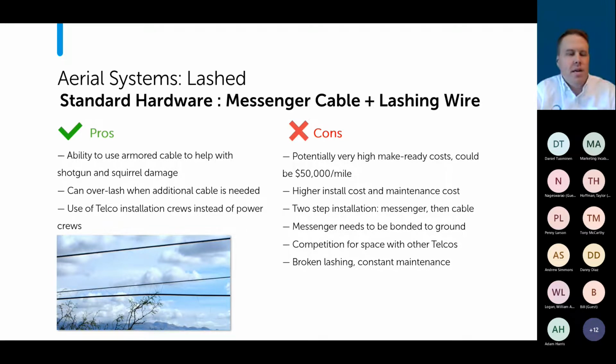You're going to have more truck rolls just to go out and relash and tighten up that cable onto the messenger cable. So again, I don't say all this just to bash strand lash as not a good approach and not a good place to put cable. There are certainly areas where it is a beneficial place to have your cable located in regard to a fiber to the home build. But again, it's all very dependent on your particular situation, what your pole structure looks like, what your infrastructure looks like right now, and then population density as well.